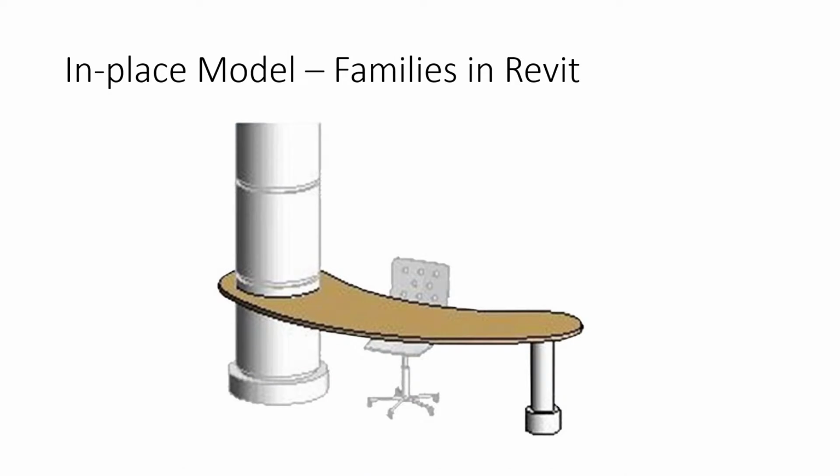Model in place family in Revit. The only difference is that a loadable family can be saved outside Revit and it can be shared separately. In case you are doing model in place, you are doing it inside the project, so you can't share it outside.